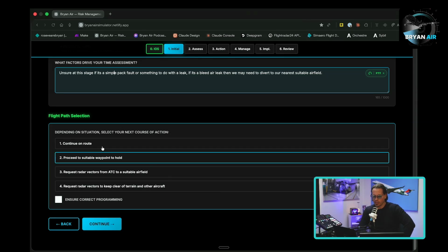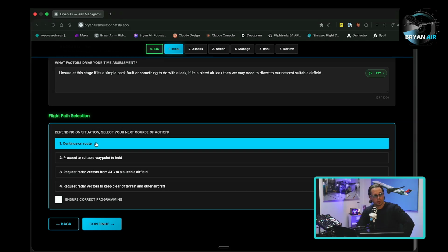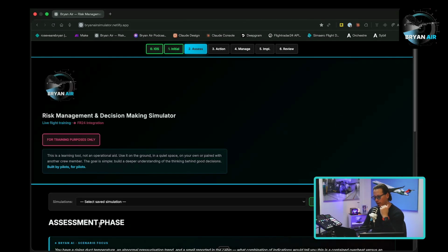What I'm going to say here is continue en route, because it is quite a long sector to Johannesburg. And although we're flying now away from Cape Town or away from our alternates, we're still not really sure at this stage what we're going to do about it. So I'm going to say continue en route. Obviously make sure that the FMS is correctly programmed for that. And we're going to go continue.